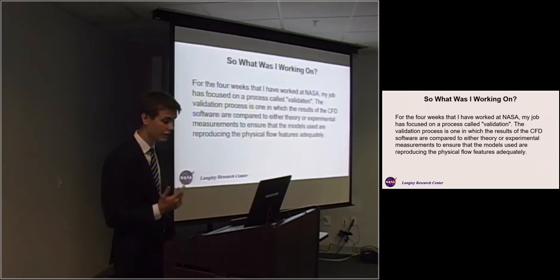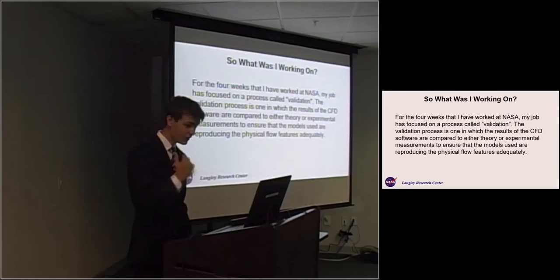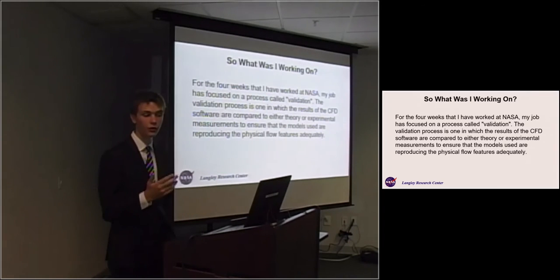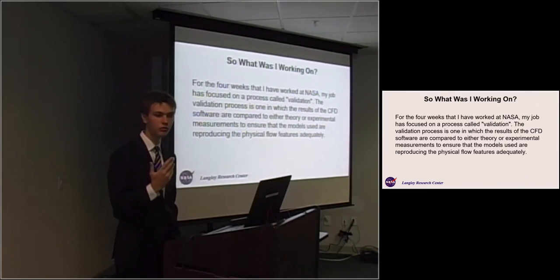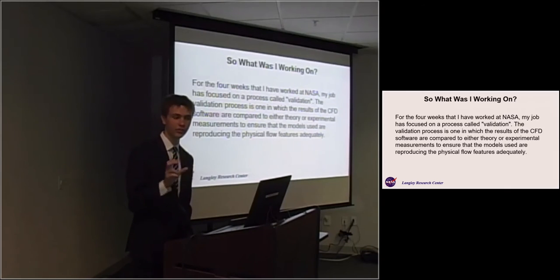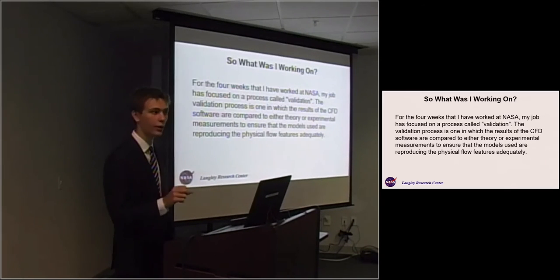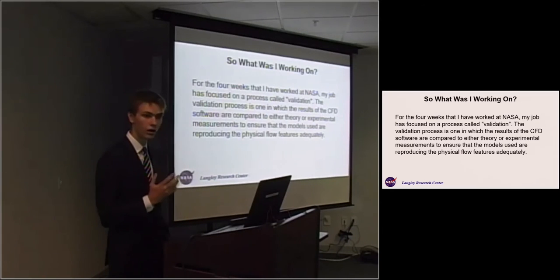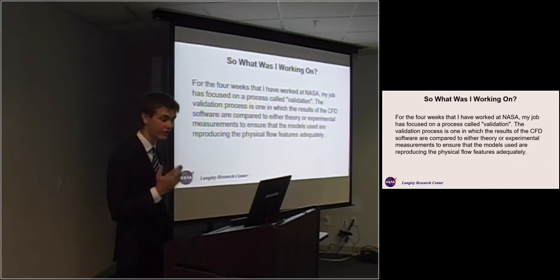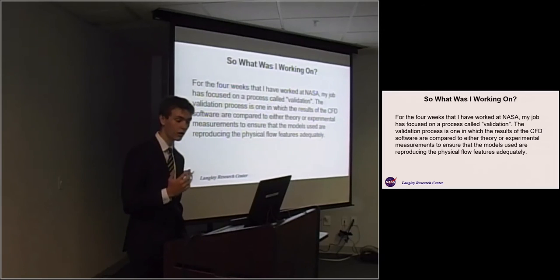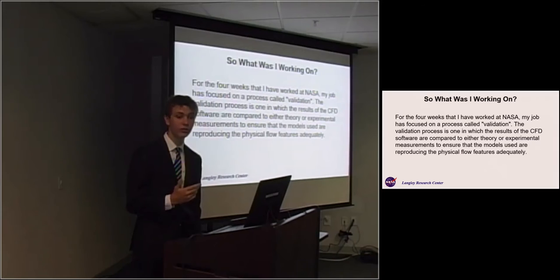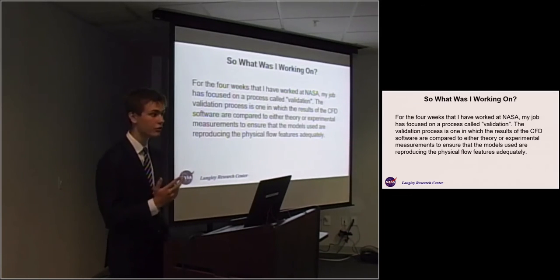Basically, we take the results of CFD software and compare them to theory or experimental measurements, other sources, things that have actually been run through the wind tunnel, and we have data that we're 100% sure of. We compare our results against that to ensure that the models are accurately reproducing our flow, basically to make sure that the models are working for our given situation.